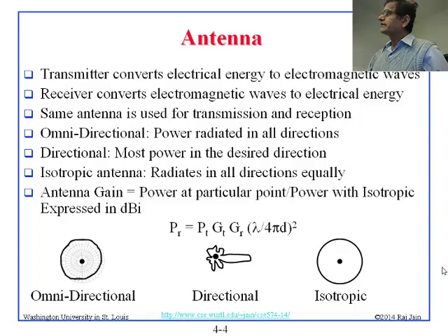But most antennas are not isotropic. Actually, if you really measure it, you will find it very close to the circle and spheres here, but most antennas are not. You will find that the signal strength is more like this, where what I have done is I have drawn a line at equal power. So if I found the power, let's say 1 watt per square inch, I just went around until I got 1 watt per square inch.